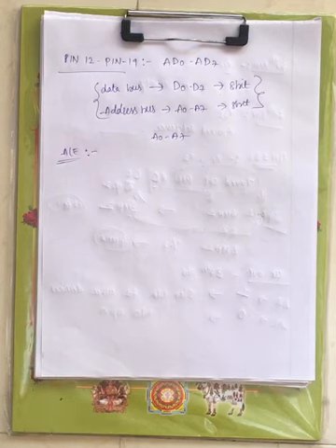AD0 to AD7 will transfer multiplexed. The lower order address and data bits are multiplexed, and at a time it can't carry the address with the data bus. It will carry them individually.